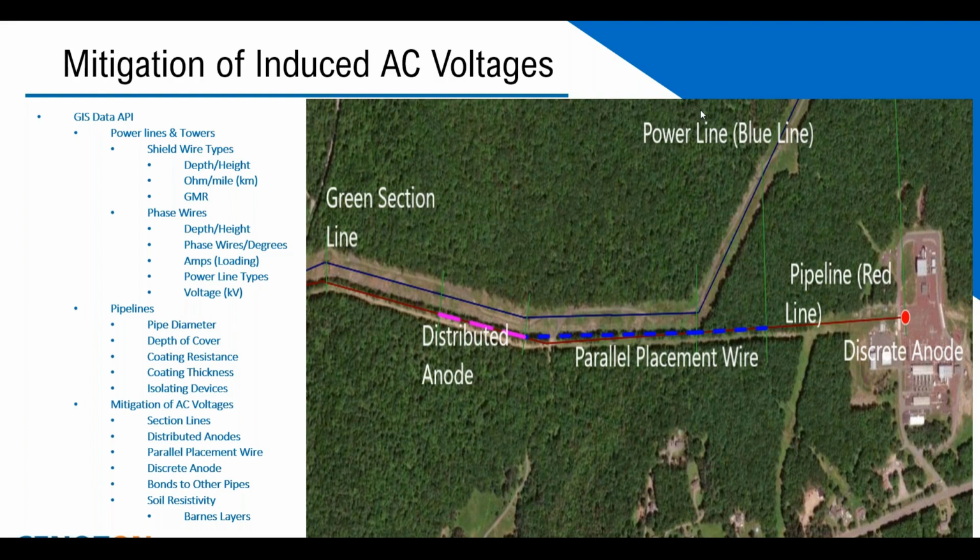soil resistivity. There are all different layers, but really when it comes down to it, there are 3 major layers. It's the layer around the pipe, which I'm going to call the corrosion layer. And why? Because that's where it happens. That's where the current density is.